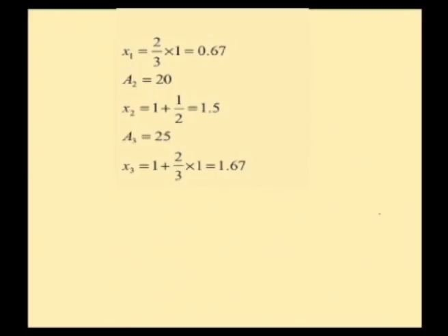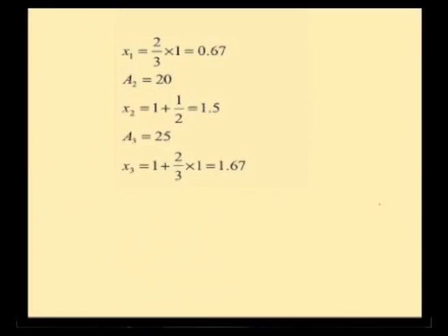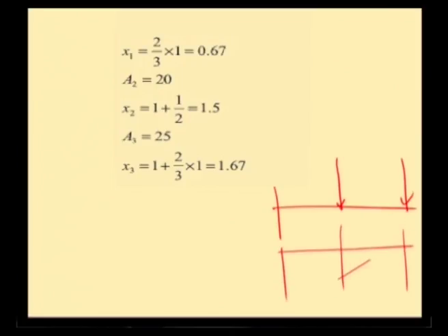Now, we have been seeing an example of a cantilever beam subjected to 2 point loads. We have divided the bending moment diagram into portions: one triangle, another rectangle, and another triangle. The first area we have computed, and then we need to find the CG distance for area 1.